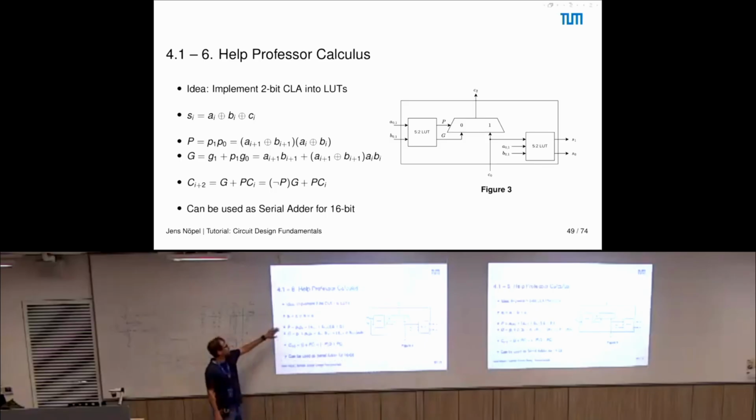We have a look at the formula here. Okay, we have 3 inputs, and 2 of them have 4 bits, making all of them 4 bits, plus 1 bit for the carry, makes 5 input bits, which still suits our 5-input lookup table, so we can use that to generate both of our output bits.